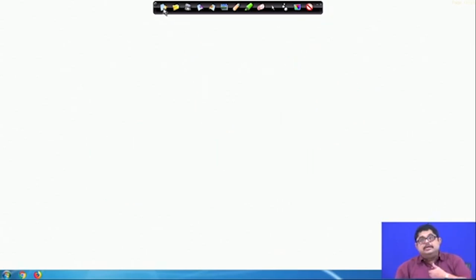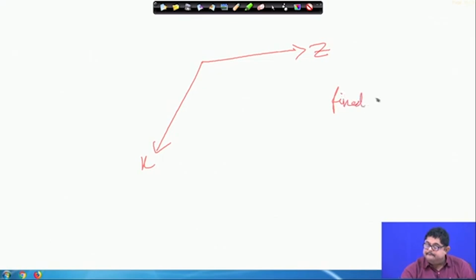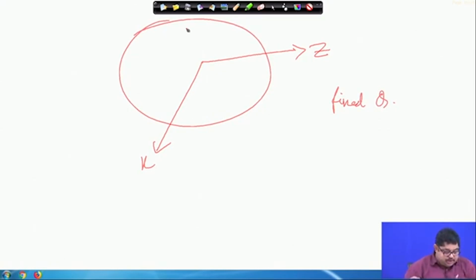Similarly, another 2 dimensional pattern will be if I fix the theta. So, fixed theta means the XZ plane, and there the pattern will be something like a circle. So, at any point if I want to find the value of S average, this is the value of S average, you see always it is the same. So, this is a theta plane pattern.